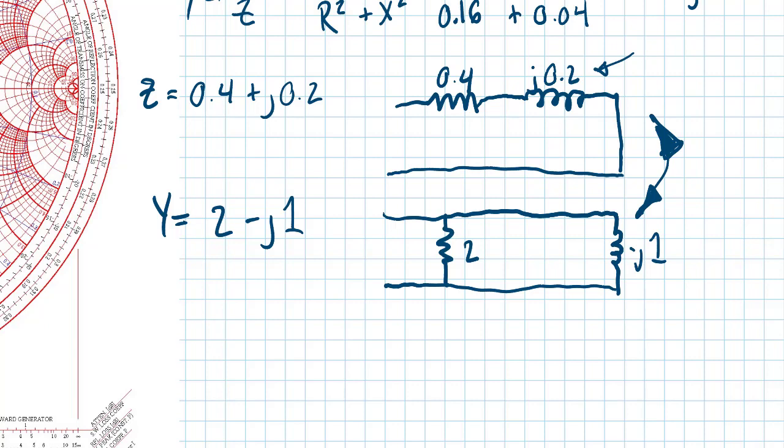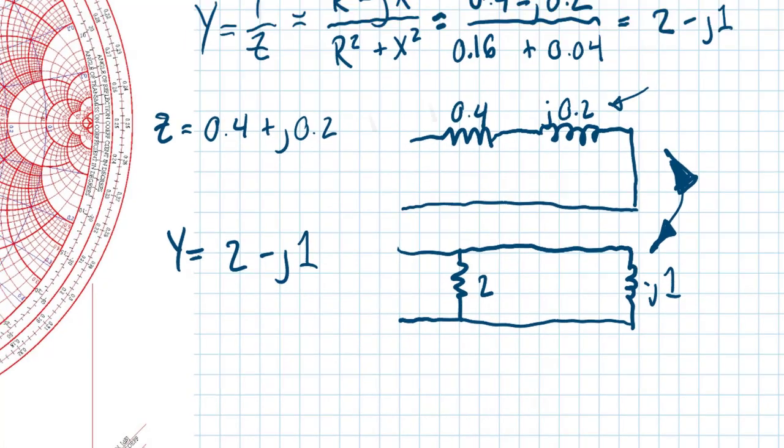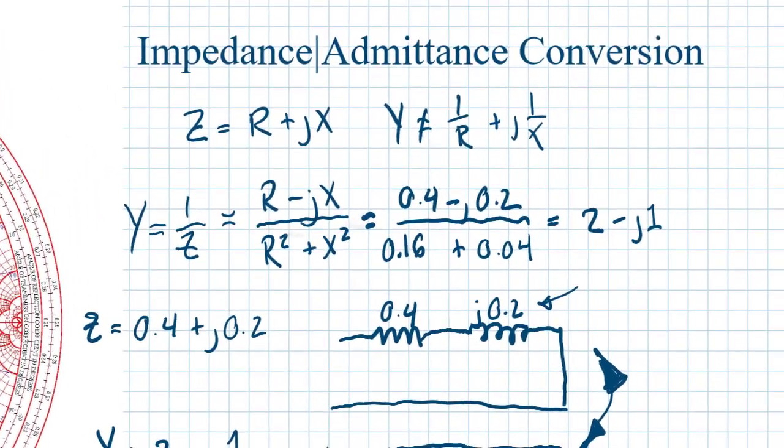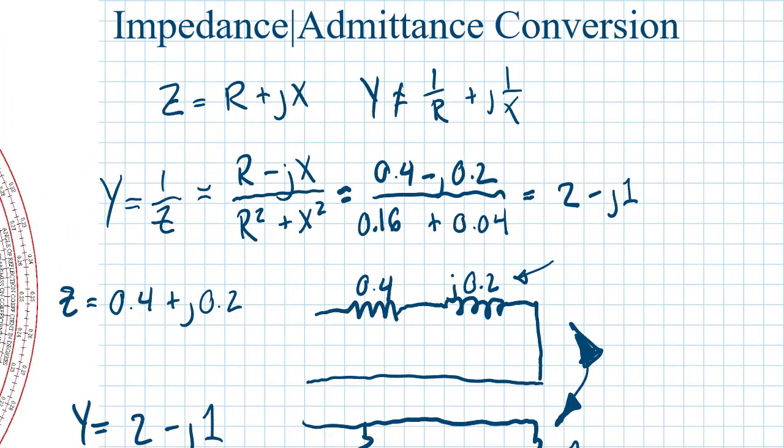All right, so that's kind of a long look at impedance and admittance conversion, but the nice thing is that it shows up graphically on the Smith chart. Bottom line is you need to follow the rules of algebra, but you can actually see the way those values play out once you know how the Smith chart works. So that can be also of interest.